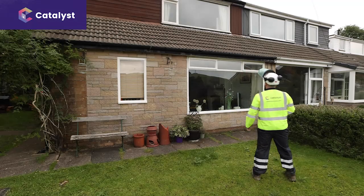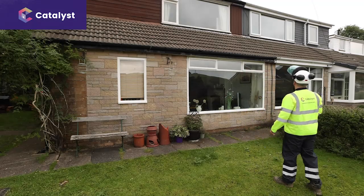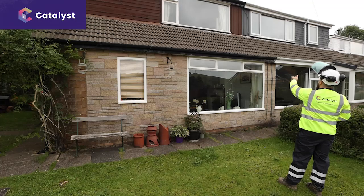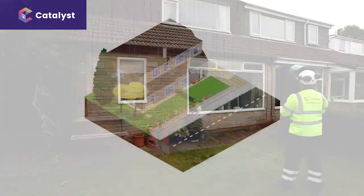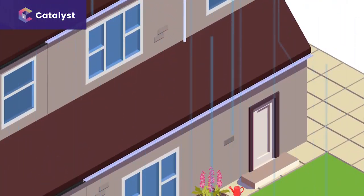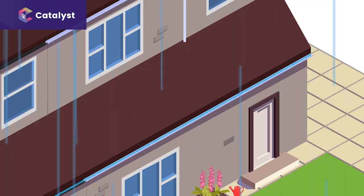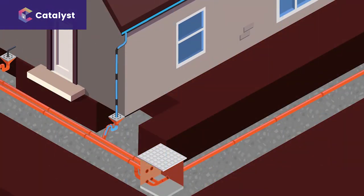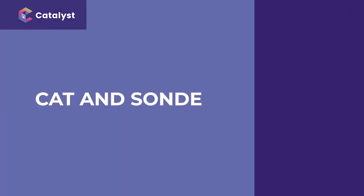Another important task is to check the gully connections. This establishes where the water it takes comes from and who derives the benefit. As we can see, this is a shared gully. It takes water from our customers' gutters and those of their neighbours. Both properties derive benefit from the same drainage system. Therefore, as it's shared, it's the responsibility of the local water company to maintain serviceability.